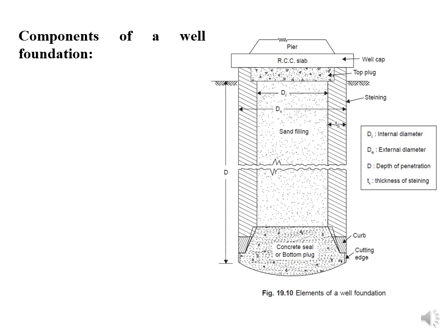You can see here a concrete seal or bottom plug is also provided. Once the installation or construction of the well is completed, we have to fill the bottom part of the well with concrete, so that the superstructure load will be distributed uniformly at the bottom of the well.